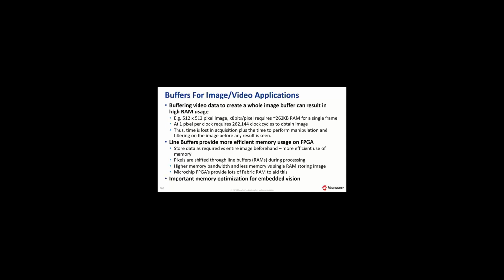So how do I look at then for making use of buffers? So if we take this simple example, 512 by 512 image, 8 bits per pixel, about 262K RAM, which we can put on. It's not horrendous. Okay, but it's still the power. I'm going to use all of my resources to do one aspect of this whole loop. So let's look at an optimal way. Equally, a bunch of time to actually fill the buffer. Then I've got to manipulate it. So I've got lots of latency I'm building in. So we'll go with putting buffers in. With our architecture, it works quite well because we've got lots of RAM and lots of buffering, which is kind of nice. So how do I make use of that?